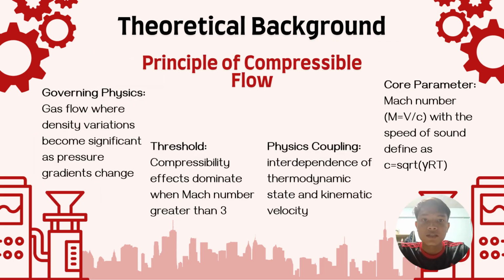Here I'll be presenting the theoretical framework for our converging nozzle analysis. We are studying gas flow where density variation becomes significant as pressure gradients change. Unlike incompressible flow, we must couple thermodynamic properties with kinematic flow motion whenever the Mach number exceeds 0.3. The Mach number, our primary governing parameter, relates local velocity to the speed of sound, which is itself determined by the gas temperature and specific heat ratio.